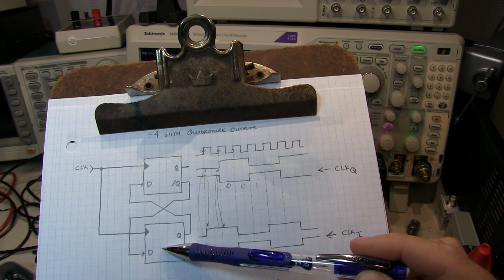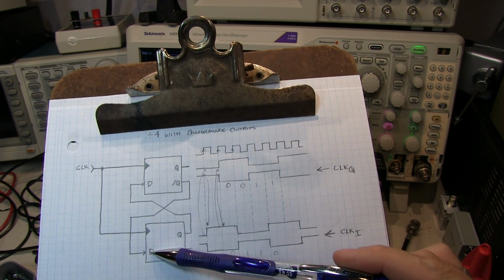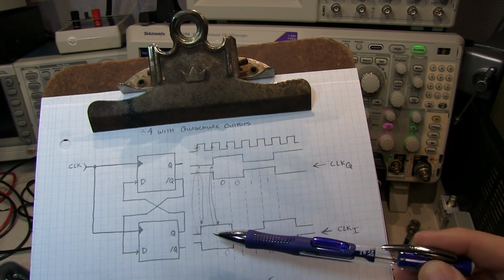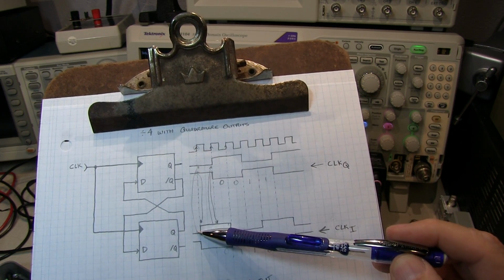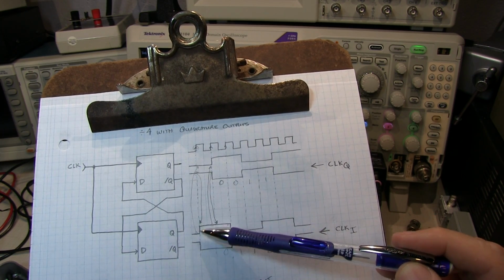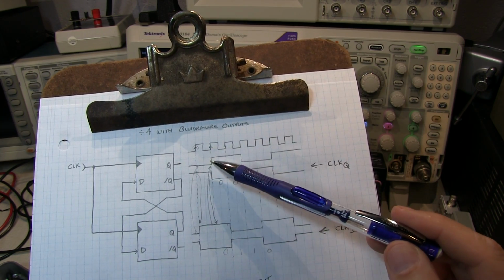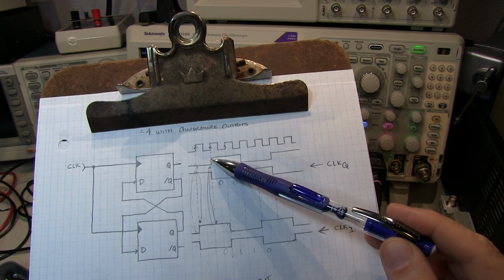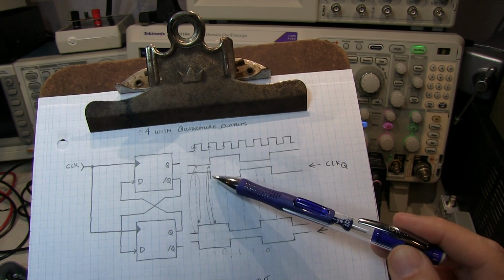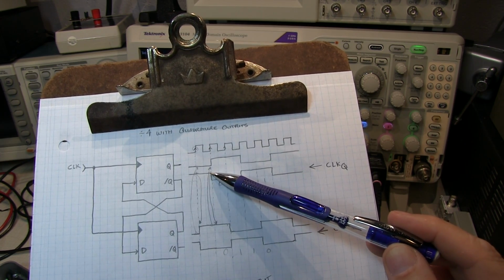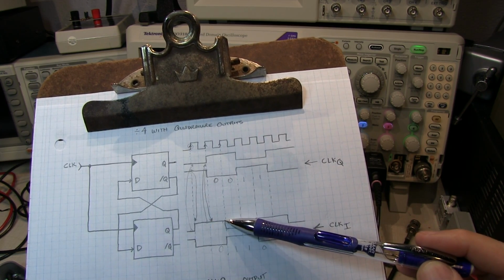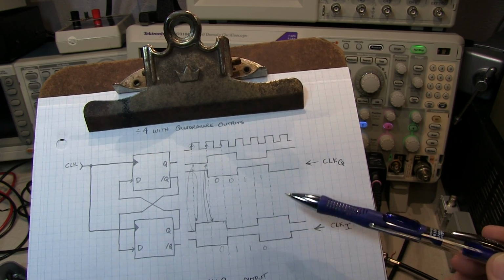Now let's look at what happens with this flip-flop. When this input goes high, the D input is coming from here, so that output is high. So this output is then going to flip. Essentially this low level here gets transferred up there, and this high level gets transferred down there. Now at the next rising edge, we do the same thing. This state changes because it's looking at this high output coming from the Q bar, so that changes state. But this one is sitting already high, so that doesn't change state. We can continue to the next clock cycle, and if you look through it, you can see how the whole thing works.